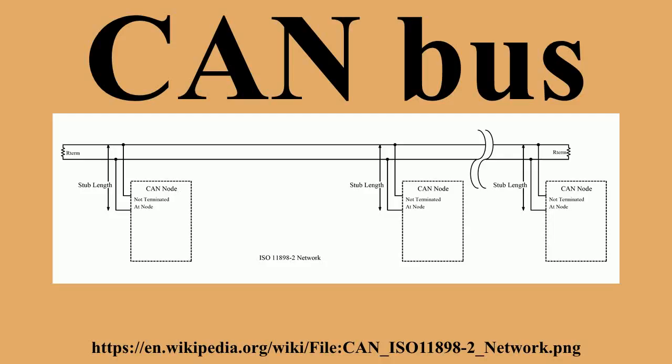Each node requires a central processing unit, microprocessor, or host processor. The host processor decides what the received messages mean and what messages it wants to transmit. Sensors, actuators and control devices can be connected to the host processor. CAN controller, often an integral part of the microcontroller. Receiving: the CAN controller stores the received serial bits from the bus until an entire message is available, which can then be fetched by the host processor. Sending: the host processor sends the transmit message to a CAN controller, which transmits the bits serially onto the bus when the bus is free.